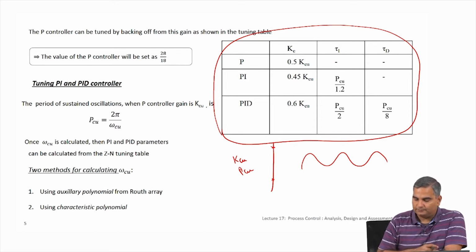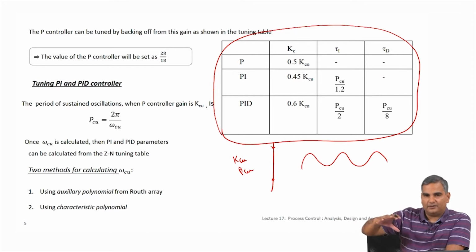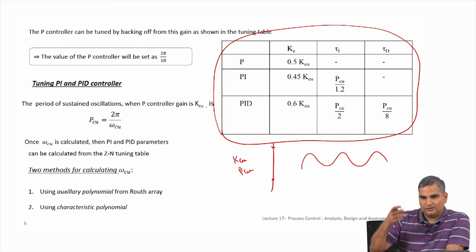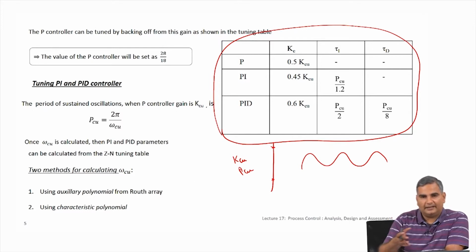An interesting thing to notice here is we never use the PI control structure for the computations we have done; you do not need to. So, we always assume that we first put in a P controller and find the limits of stability. At the limit of stability I will get 2 things: one is the critical gain at which the limit is reached, and then at that limit, because there will be roots on the imaginary axis, I will have a sustained oscillation, and I can compute the period of that sustained oscillation. Once I have those 2, I can directly write the PID tuning parameters as a function of this.